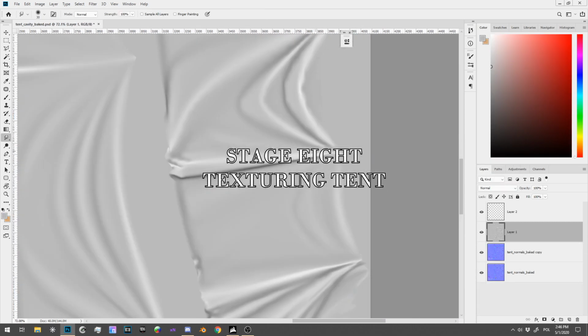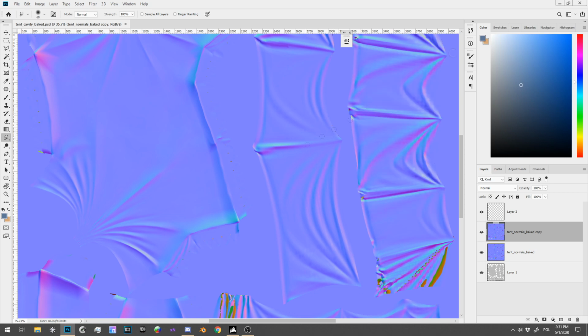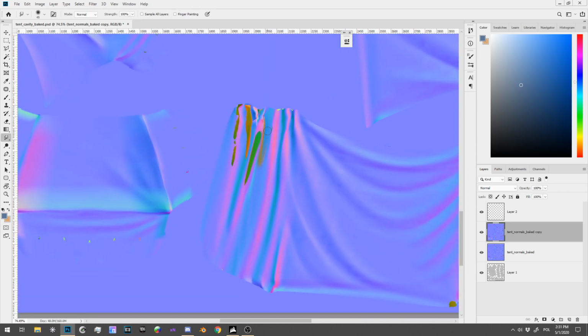Load cavity map, normal map and UVs into a new 4K resolution Photoshop file. Since they have some visual glitches, smooth them out with a smudge brush. Next, based on the fixed normal map, bake the ambient occlusion. Let's use the free XNormal program to do it.